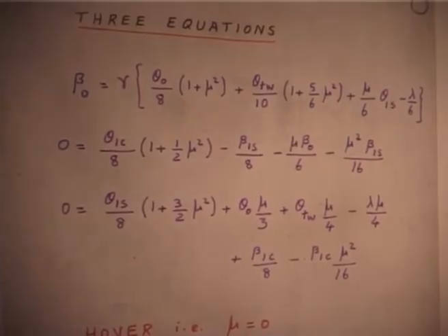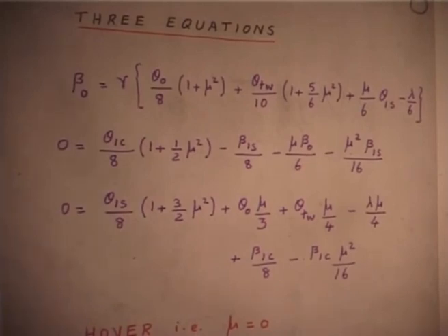If I do not know that, then what will I do, that part we will come to later. That is what the trim analysis is. The entire trim analysis is related to iterating between flap motion and then fuselage equilibrium. So, you have to keep going back and forth, that is why it is a complicated analysis, okay. Even the solution procedure is a little complicated. This is the very simplest, that is what I am showing.